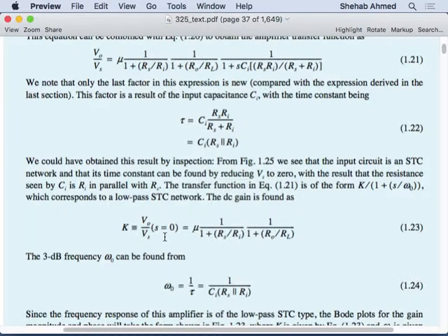Capacitor is an open circuit. If it's an open circuit, do the same voltage gain work that we did last time with only resistors. No need to add the capacitance and admittance and S from the beginning. So do that to calculate K. If S is equal to 0, this is K. So plug S equal to 0 from the very beginning, and then you will end up with K very quickly.